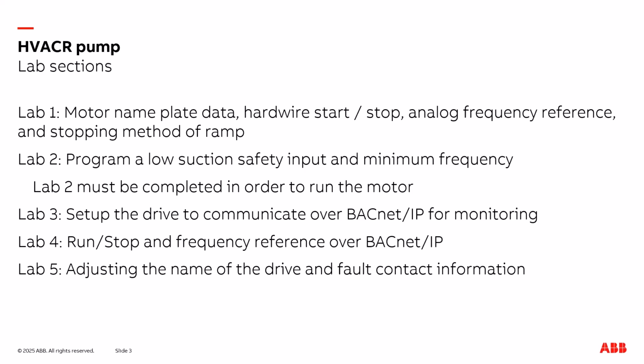In lab 2, we're going to program the drive with a low suction safety input switch, and we're also going to set up the drive to have a minimum frequency reference. Now, you must complete all the way to lab 2 in order to be able to run the motor. If you just complete lab 1, you will not be able to run the motor, just as an FYI.